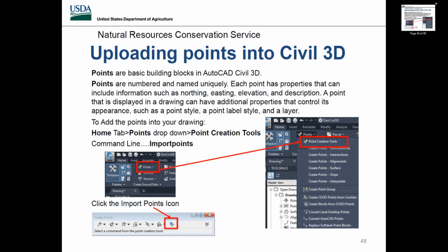Obviously, when you go out and do a survey, a lot of people don't realize how important a survey is. I can't explain to folks enough that you can't have too many points by any means. Well, you can, but technically speaking, the more points you have, the better surface you're going to get. Amen. And as far as all the different grade breaks and things like that, we have a lot of new folks that have come aboard, and I can only tell you from experience, when working with the seasoned technicians out there, ask questions. Ask them why they're taking that shot, or what you should be looking for as far as shots. There are a lot of shots out there that are missed, and it'll really throw off your entire design.